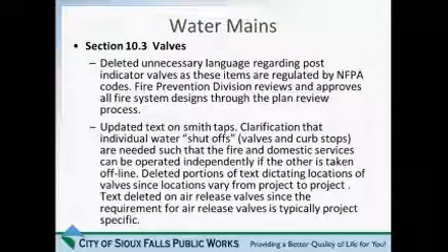On the distribution side, the side that I took a look at or review with my plan review process, I just made some text changes as to the locations of water main shutoffs. If we have a single service that runs into a property to serve both the fire line and the domestic line, I wanted to make sure that we had valves located such that each system could be independently operated. By that I mean if the fire sprinkler system had to be taken offline for maintenance, it didn't entail that the domestic had to be taken offline as well.